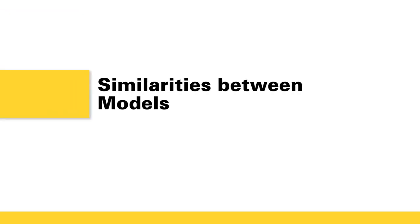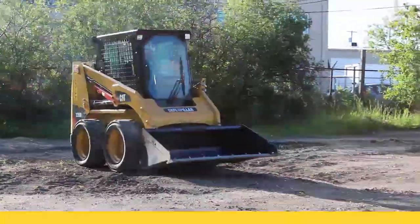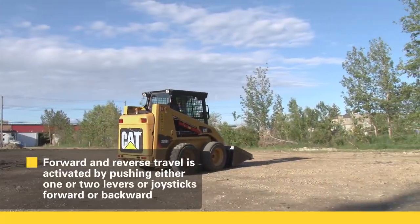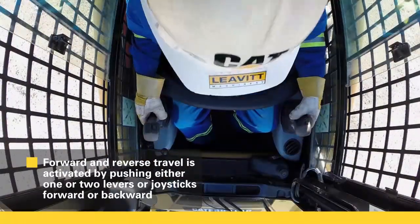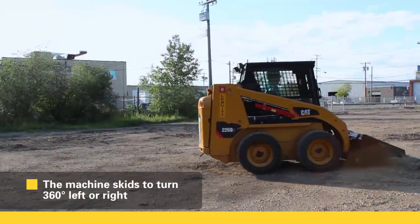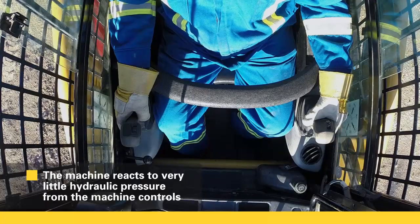Similarities between models. Although skid steer loaders may vary from model to model, all skid steer loaders have a few common characteristics. Forward and reverse travel is activated by pushing either one or two levers or joysticks forward or backward. The machine skids to turn 360 degrees left or right, and the machine reacts to very little hydraulic pressure from the machine controls.